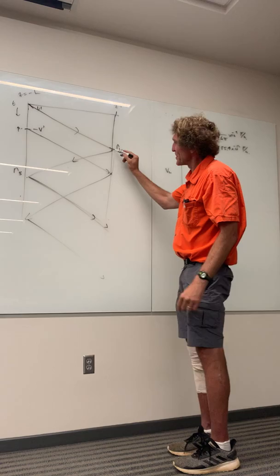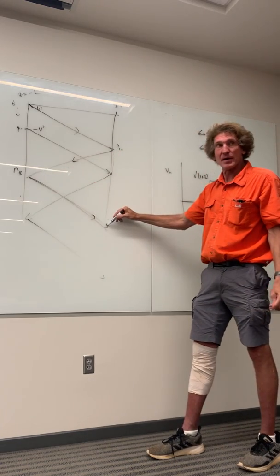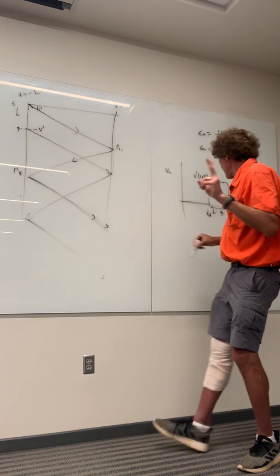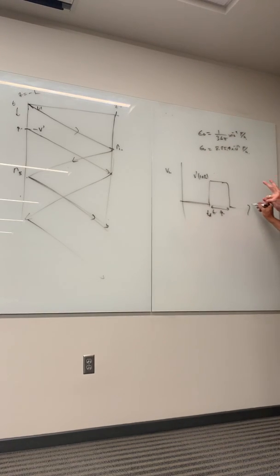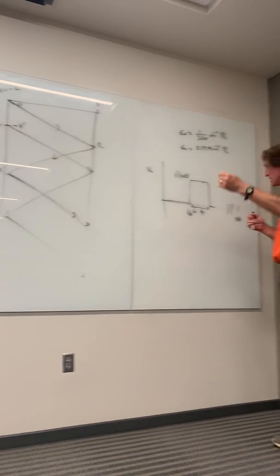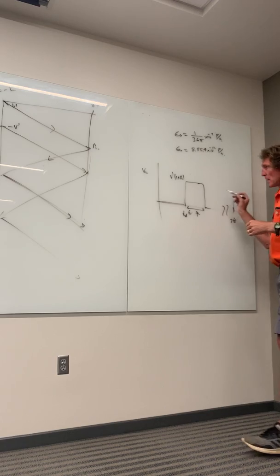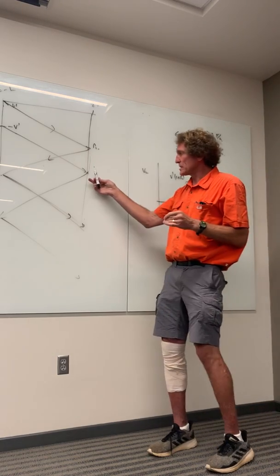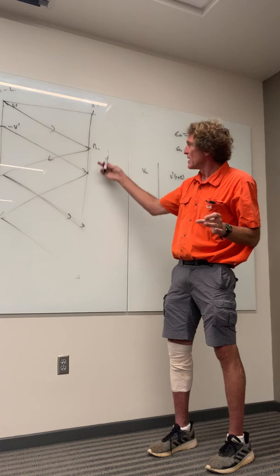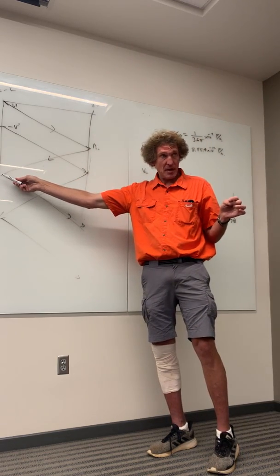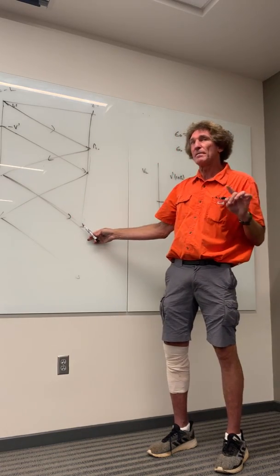And then you go down here and bang, bang here, right? Which is what? Well, that's 2 time constants go by. Now I'm out here at, there'd be a break in this line. Now I'm at 3 TD, where the TD is associated with the time it takes to go down the line once. And then I have the same thing, only now what happens? Now the value here, remember it was 0, right? So now I'm going to have gamma L times V prime times gamma S, right? And then it's going to be times 1 plus gamma L.